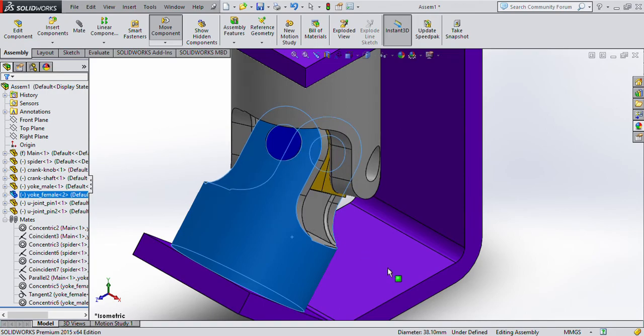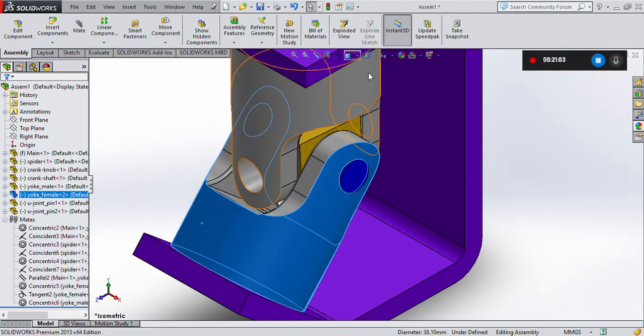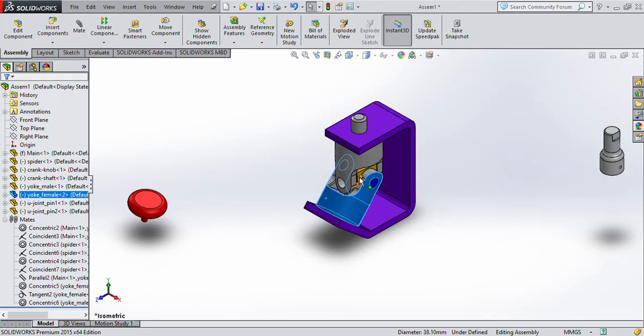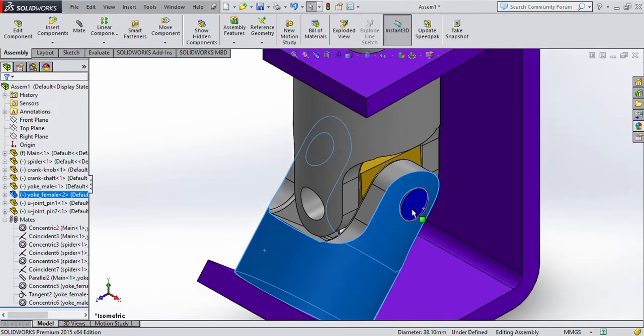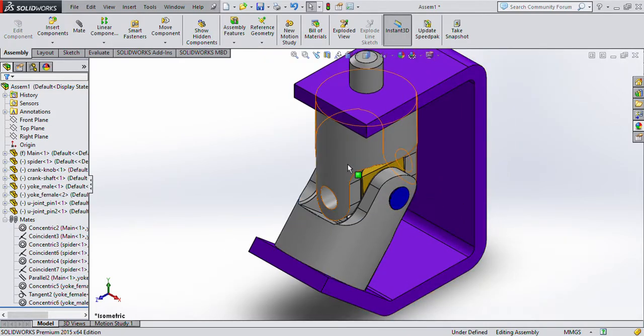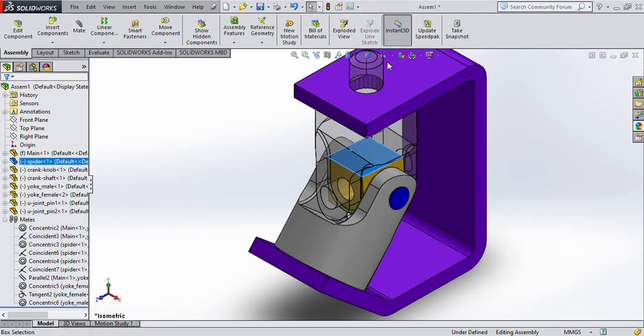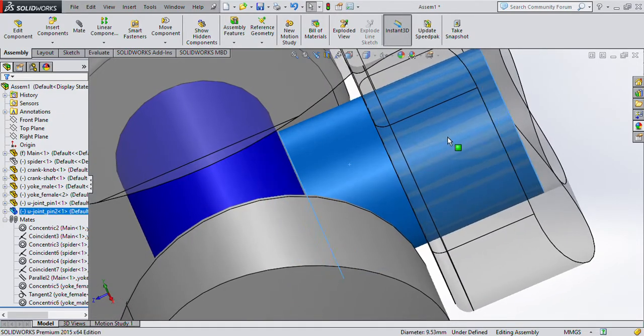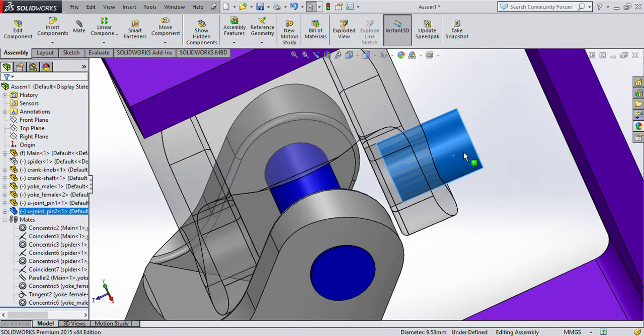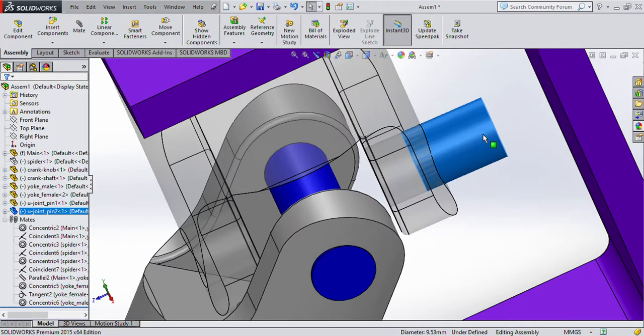Okay, now that's why you should, particularly when the part contains many components, this is a main issue. That's why we may right click on the components and hide the components. Okay, change transparency or hide component. If you hide the components, you can see my component is here, and you can bring the component back to the suitable place.